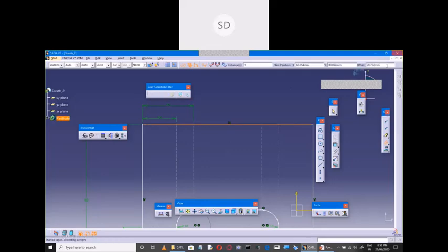Offset, I'll select this line, minus 20. Now I'll take a circle here. Just snap to the intersection point. You can just observe here. Now you got over constrained dimensions here. Is it right? Now the diagram colors are changed. Okay, let us go for trimming now. Right.